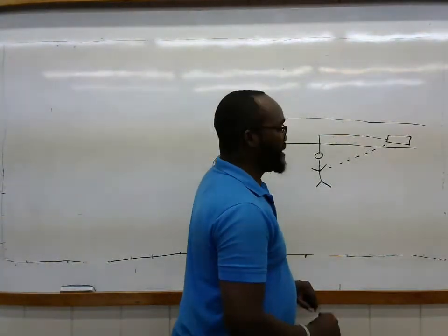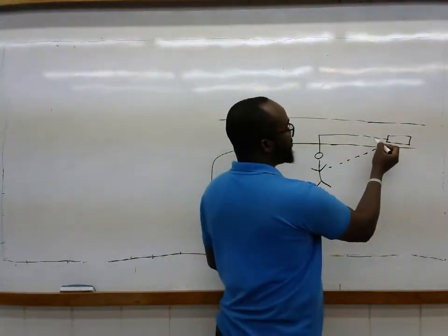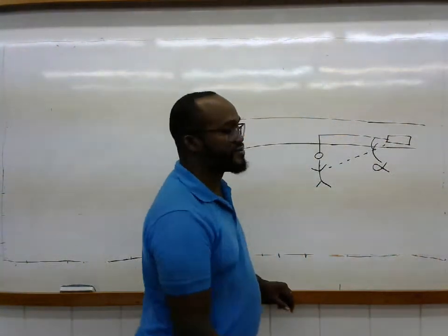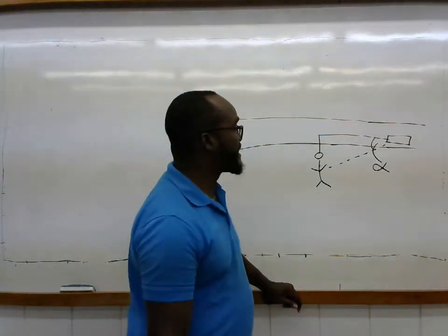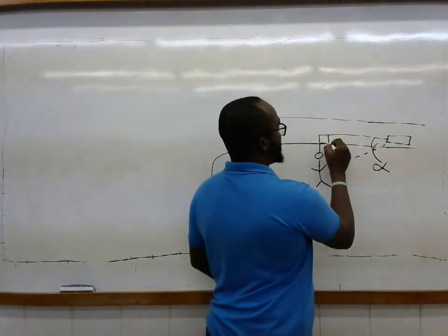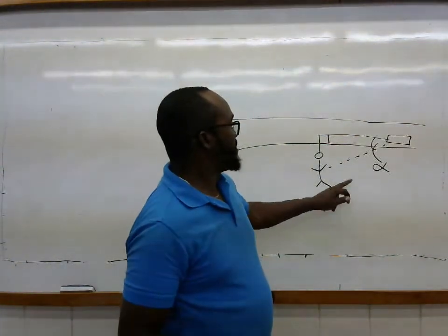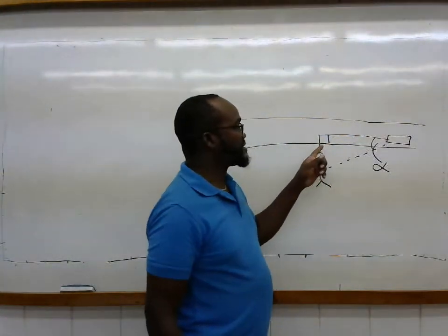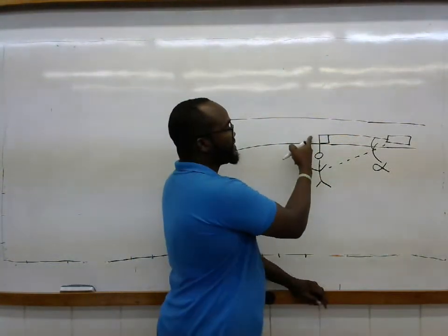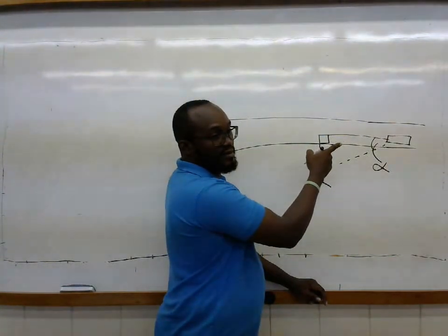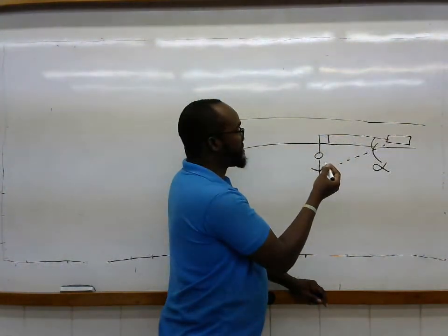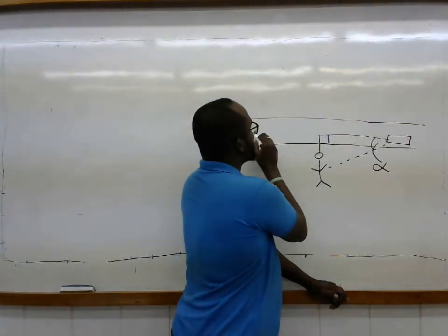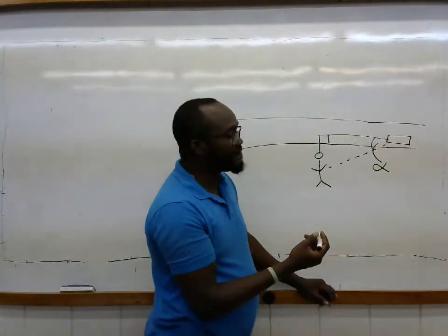observations. I would have mentioned to you guys the importance of that because of what we refer to as the cosine effect or the cosine error. Right? Being, of course, it's impossible, or I shouldn't say impossible, impractical, to measure speeds of the vehicles straight on. Otherwise, it would be dangerous to be knocked down. Can't stand in the middle of the road, obviously. So we have to stand at some distance away from the roadway or the traveled path of the vehicle.